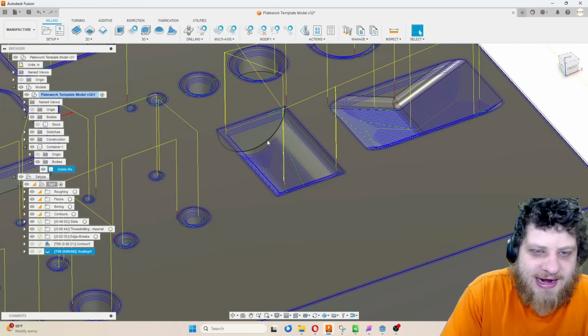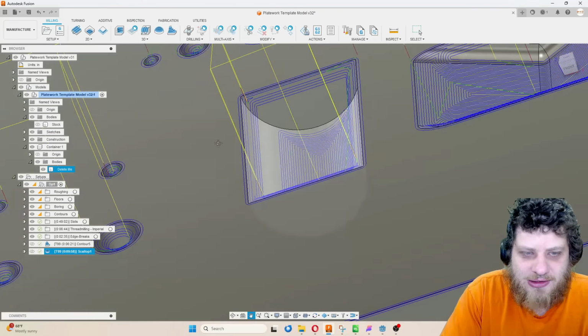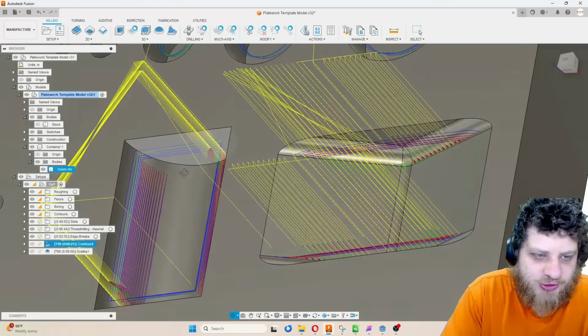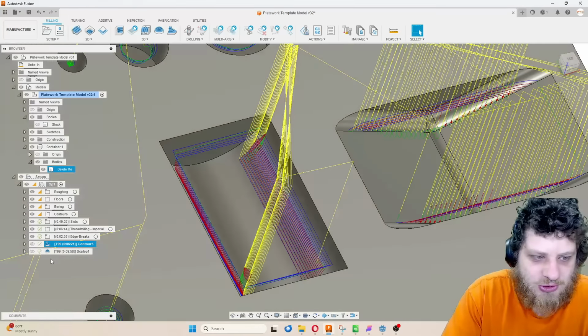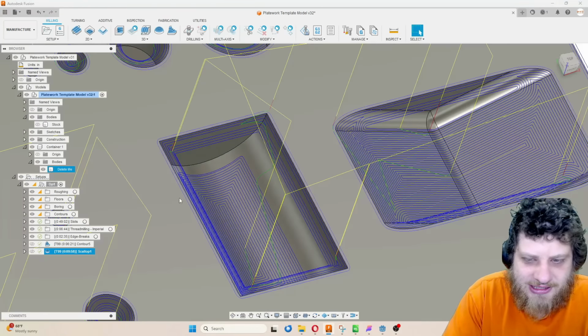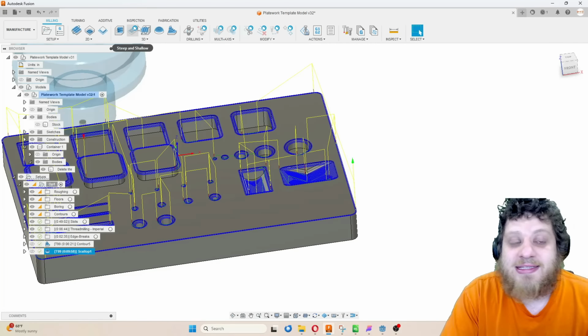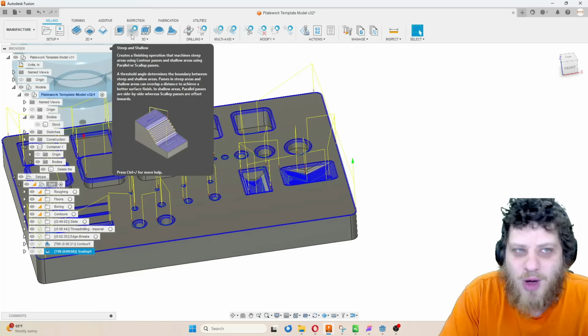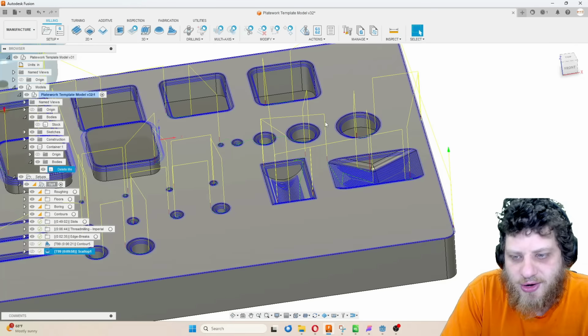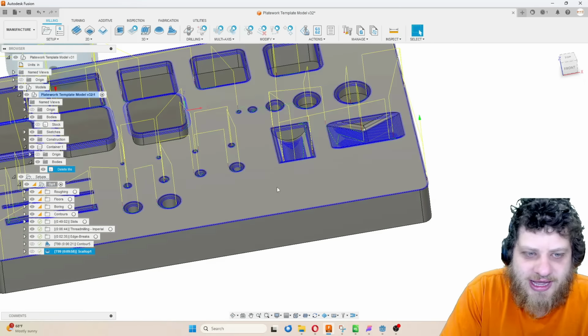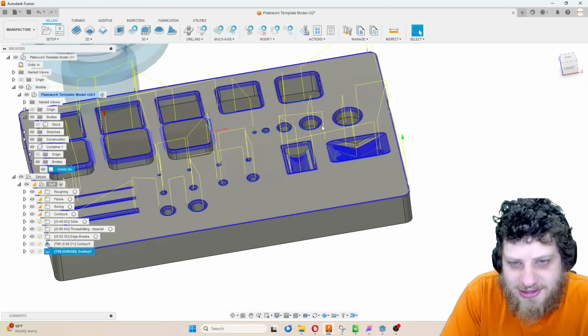And this should grab everything that the ramping toolpath or the contour toolpath missed. So this is getting those walls there, and then the scallop here is getting the floor. Essentially what we've done is we've recreated the steep and shallow toolpath, which requires the manufacturing extension. Though, again, scallop has grabbed all kinds of random stuff that we don't want it to grab.